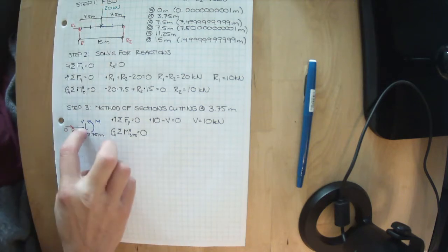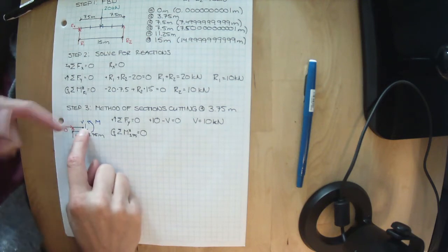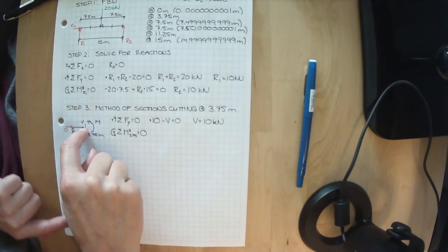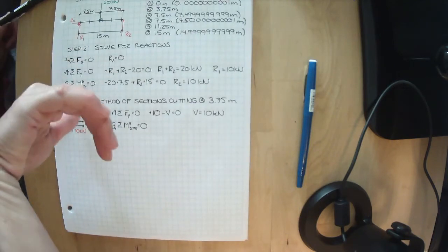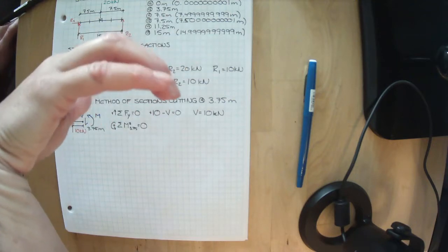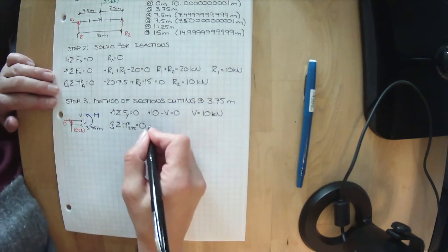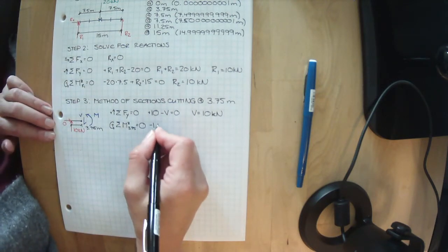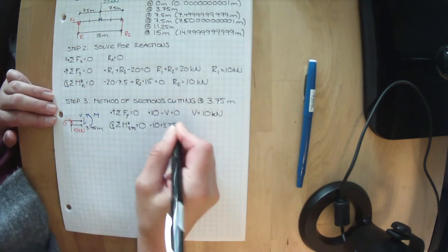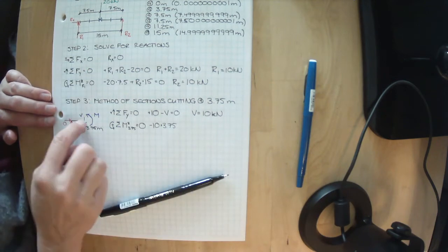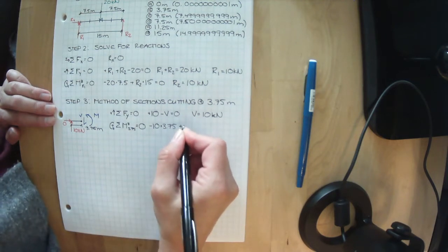So let's see, if I put a thumbtack here, the shear is passing directly through it. That's 0 kilonewtons. We have 10 kilonewtons pushing this way. That's trying to make it spin in that direction. If I curl with the fingers of my right hand in the direction it's spinning, my thumb tells me that that is negative. So minus 10 kilonewtons, and it is 3.75 meters away. Shear is passing through it. All I'm left with is my unknown moment. So I've drawn it positive.